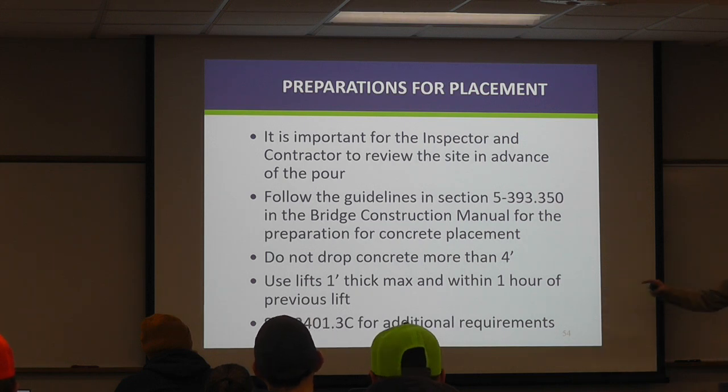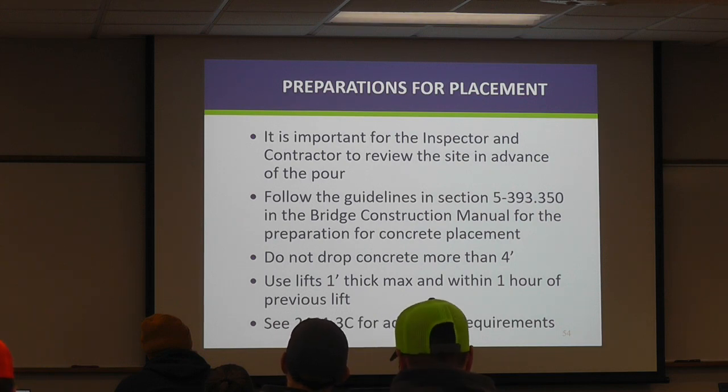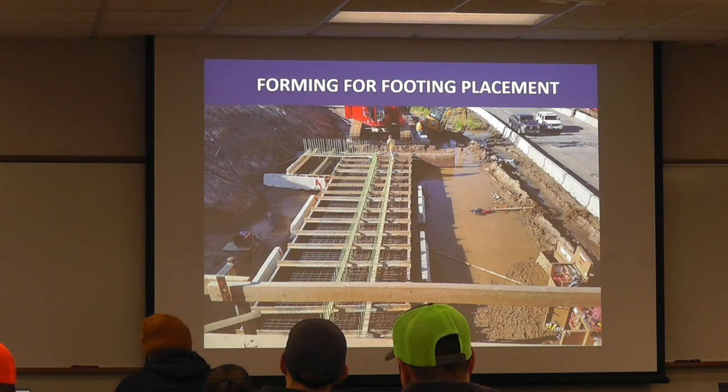But we also want to, so we put a lift on there, and we want to come with the next lift within an hour. Otherwise, that first lift will start to harden up. But we always want to vibrate, so you get the lift in there, and then say 30 minutes later you come back. You want to vibrate so that we are going down into the previous layer as well. So in 2401.3C, there's additional things that can happen there.